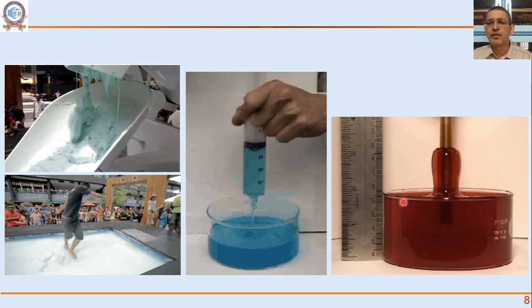Viscoelastic fluids. The Weissenberg effect, rod climbing effect. You see the rod and you don't get a vortex, you get a rod climbing effect. Again, this is because of the viscoelastic nature of the fluid. So fluids have very dramatic properties which, if you don't understand properly, can give you a lot of trouble when you start designing plants and equipment and so on and so forth.